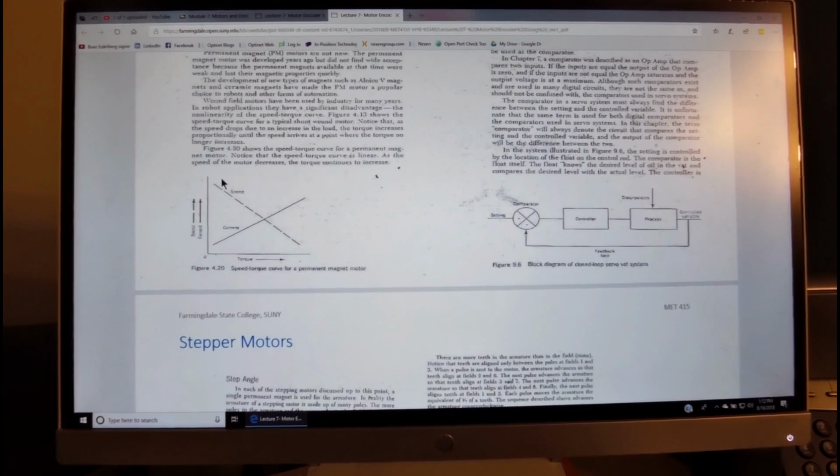As one is increasing, the other one is decreasing. We can choose motors with various combinations of maximum torque and maximum speed. One factor which is the same is the power. The power is the product of force, or torque, and speed, and therefore when the power is constant, when one is coming down, the other one may come up.